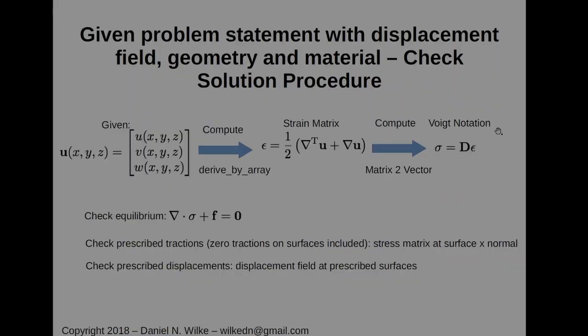Okay, so that is just a reminder of this Voigt notation, and that's stuff that you were able to do quite comfortably. So that's what I'm just putting here, matrix to vector. And then we get the 6 stress components. So this by construction will be a symmetrical stress tensor, okay, because this is symmetrical, and that also implies the types of materials that we have do not have embedded moments or pointwise moments that are present there. Okay, so that is the assumption, and in any case, this is valid for 99.99% of materials.